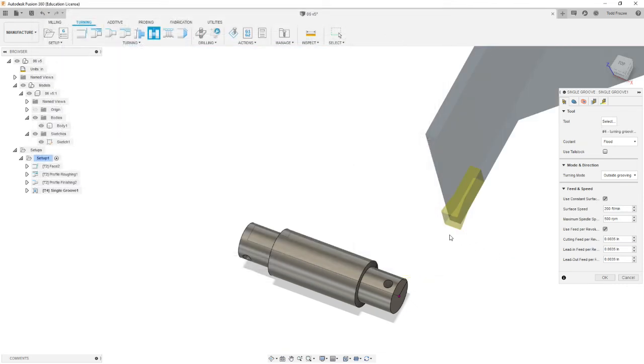And it's called square. The inserts still have a really tiny radius here, but this is a very small part, and I think it's something like a 4/1000 radius. It's really tiny. So that's the sharpest tool we have. You probably can grind a truly sharp tool if you're going to use high-speed steel, but this library doesn't contain one that's absolutely square.